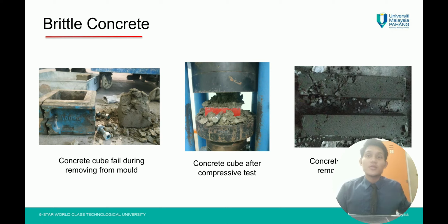So this picture shows how brittle the concrete is for the trial and error mix design for 10% replacement. The first picture shows the concrete cube failed during removal from the mold. Next picture shows the concrete cube after the compressive test. It looks massive, and the last picture shows the concrete prism failed during removal from the prism mold.